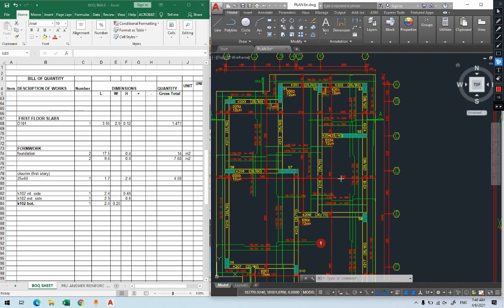There's one slab here, one will be here, one is here. 3 slabs we have it. Remember, this is a slab between the beams. A slab like this. There's a slab here, and there's a slab here. So this beam is linked to 3 slabs. Well, luckily all of them are 12 centimeter, so you don't have any problem with the height of the formwork.